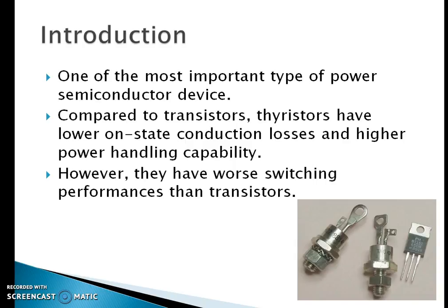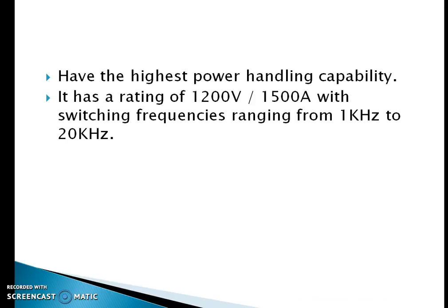Now we are going to discuss SCR, which stands for Silicon Controlled Rectifier. As we are going to discuss the details about the SCR, I already mentioned that it has high power handling capacity, up to 1200 volts and 1500 ampere, with switching frequency ranging from 1 kilohertz to 20 kilohertz.